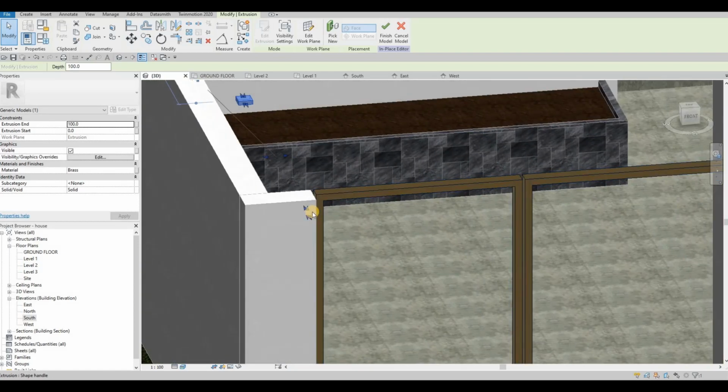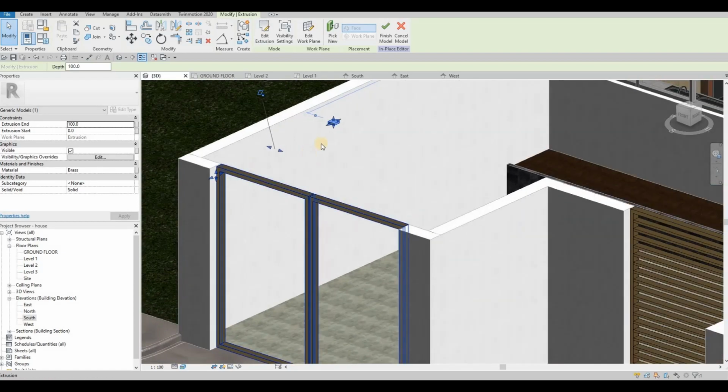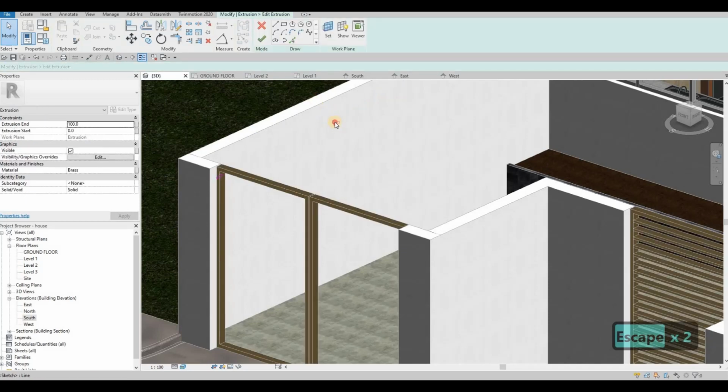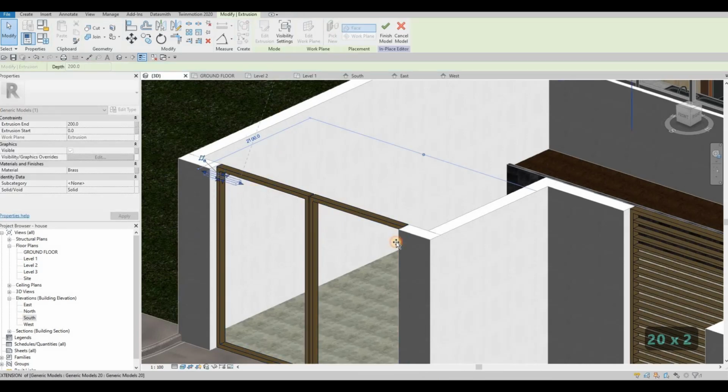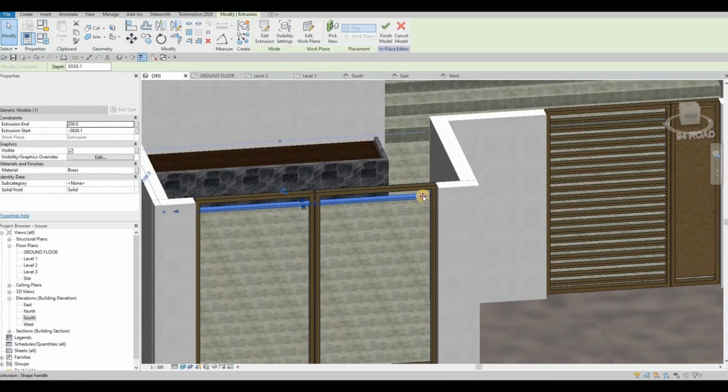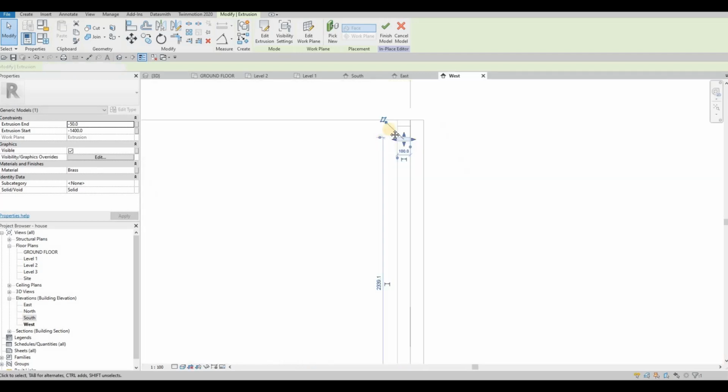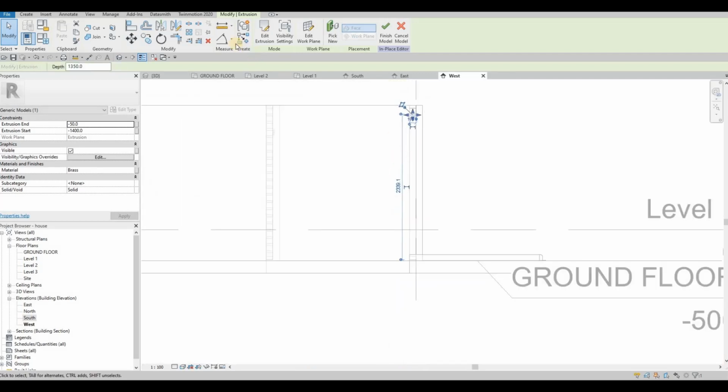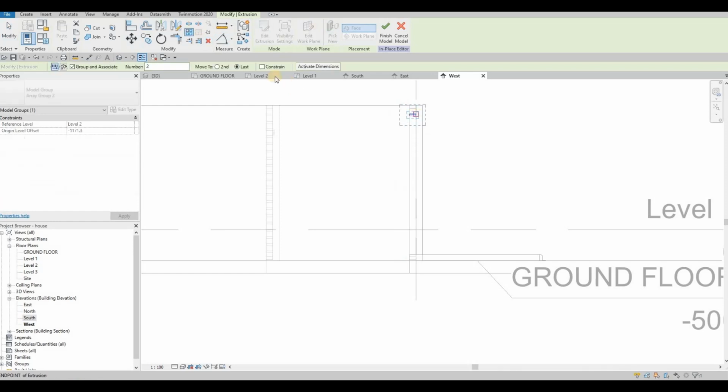So we need to copy everything. So edit this part right here, delete this to 200 so that we could see where the arrow is. There we go. And then here, and then go back right here, and then we need to array last and then 20.